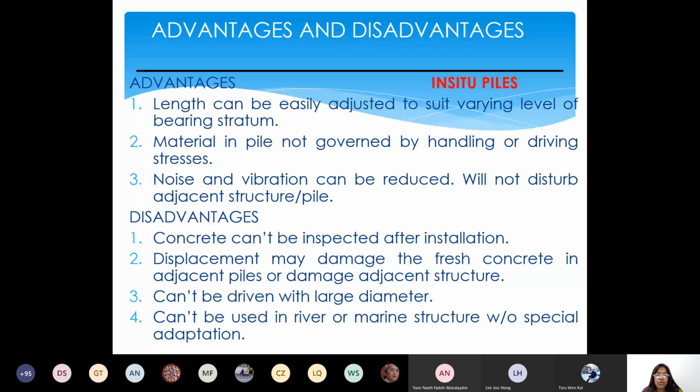It is not unique. Every foot has a different type of structure beneath the ground and also on the ground. So the sampling points that you have chosen on the ground will not be uniform for a building, right? It may be changing, it may be varying. In that case, if you are using prefabricated concrete piles or wood piles, you'll be wasting your money. But with this type of cast in situ, the depth of foundation can be adjusted, or you can decide it according to the points that you want to construct.